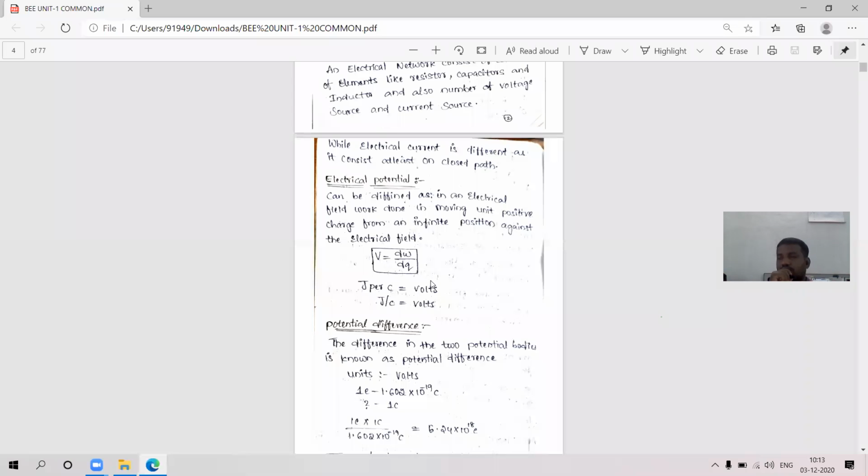You can measure that by using a multimeter. You just place the multimeter in the socket. You can observe the voltage, like in our household it is in the 220 to 240 volts range. That means one is phase, another one is neutral. Phase is 240 volts, neutral is 0 volts. That is the difference. Potential difference means 240 minus 0, the voltage will be 240.